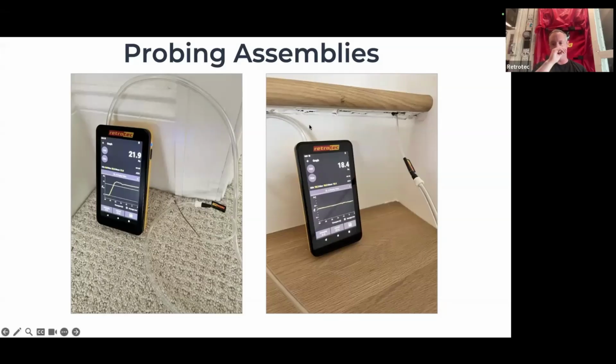This picture here on the right is an interesting one. You can see these steps have had some problems. Interior staircase here, where they've gone in and caulked it a few times after it separated the tread from the riser. I didn't have to make that hole. It separated again after another wet season that we had, and I was able to get that probe way in there. I was running the blower door, and you can see we were getting a pretty high number again. We're getting close to 20 there. We shouldn't really be seeing that. The staircase is not on an exterior wall. It's in the center of the house.